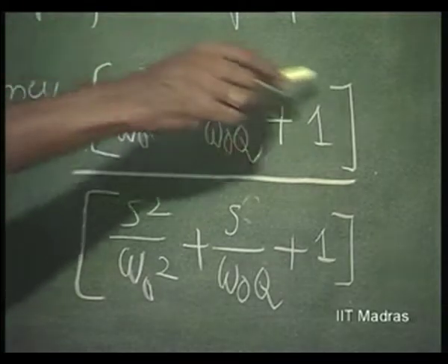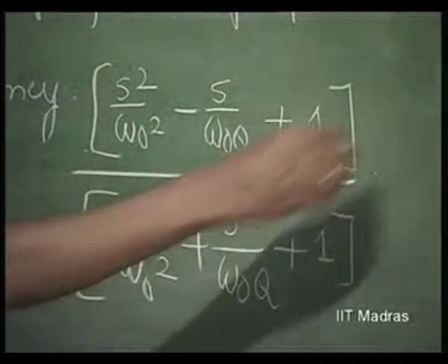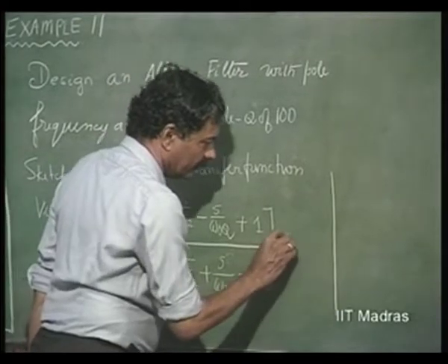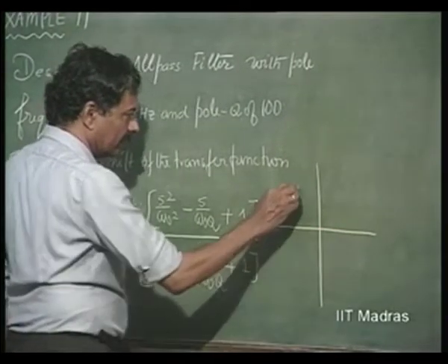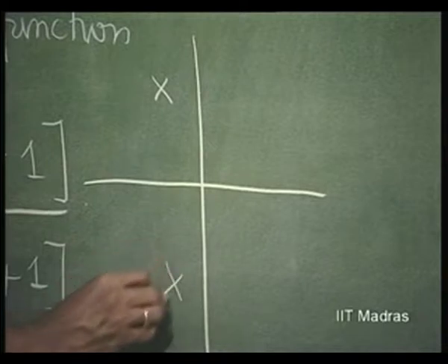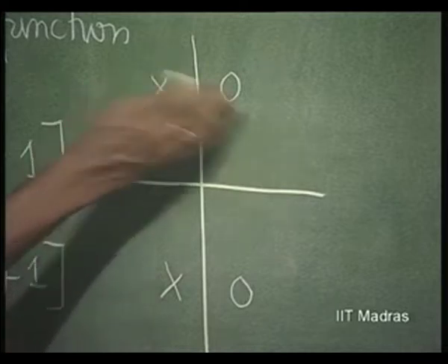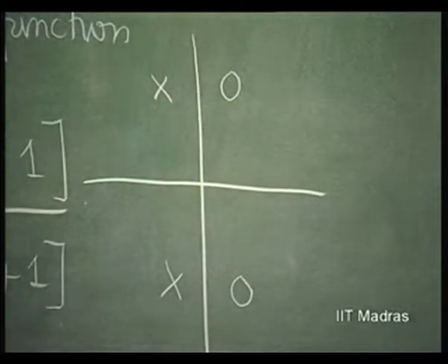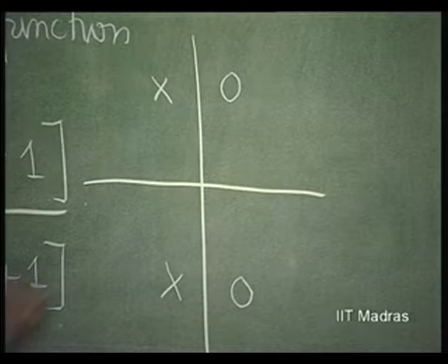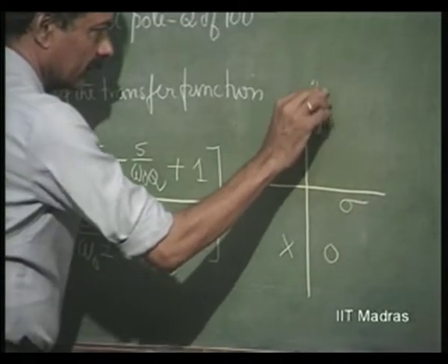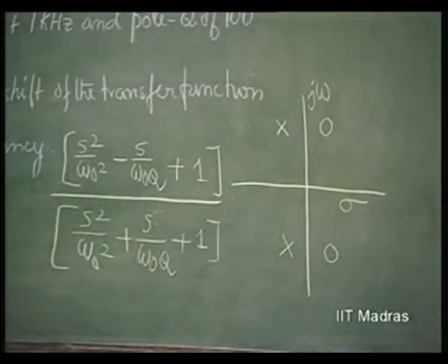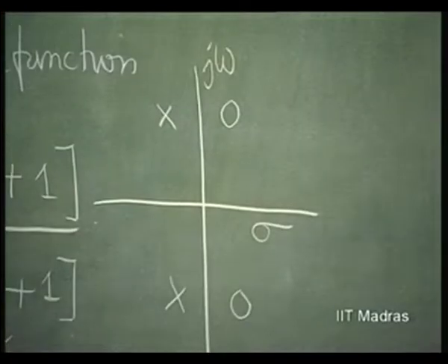These are therefore the zeros. If you plot these zeros actually in the S domain for an all pass, you will see that there will be complex conjugate pair of poles if the Q is high, and there will be a pair of zeros, mirror image of poles. Okay. So, this is going to be in S domain, the location of poles for an all pass transfer function. What is it going to be used for is first something that we will discuss.